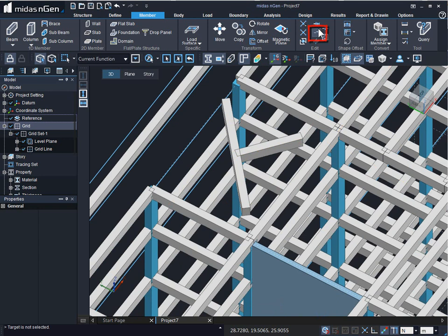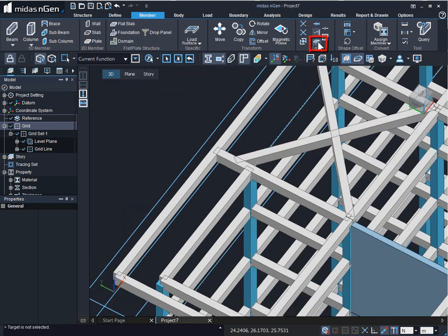Then there is extend. Extend as in we can simply select a beam that can be extended at a particular distance. So before we click on that beam, we can see in a dotted line how it can get extended. So it's like we can put the mouse cursor at the ends and then see where the extension can take place. Then there is divide.